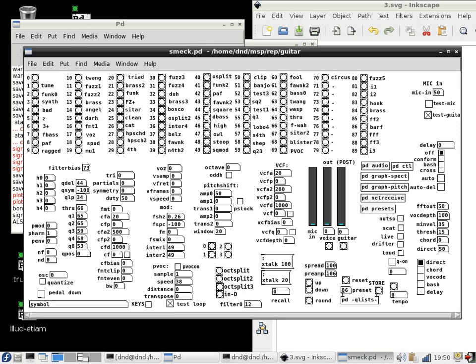One thing that you can do, if you don't mind another 20 milliseconds of latency, is peak track it, pull out the peaks, do a peak versus noise separation, leave the noise alone, and then use the peaks for whatever process you're doing, and then add them afterward. Then all of the noise will just come out like it went in, but everything else will get processed. Works with some kinds of sources, not with others, and your mileage may vary.